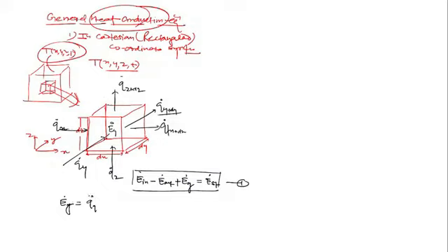What is q dot g? Listen, q dot g is the volumetric heat generation. It means it's watt per meter cube: in unit volume, how much heat gets generated by the heat source. There is a heat source within the material, and this may be a nuclear source. So this heat source may generate energy per unit volume.